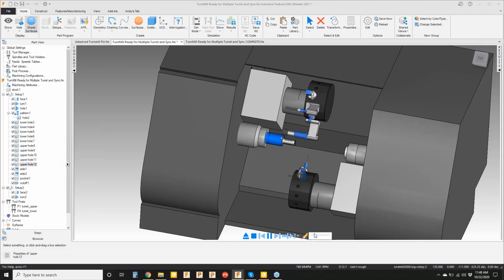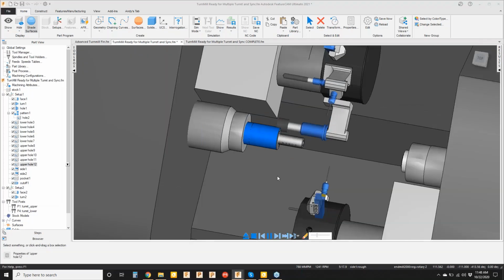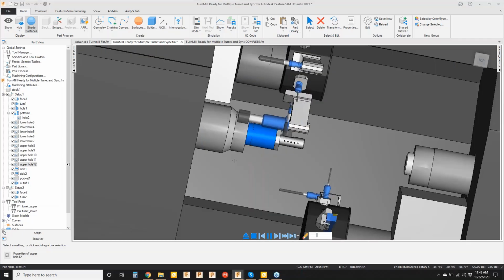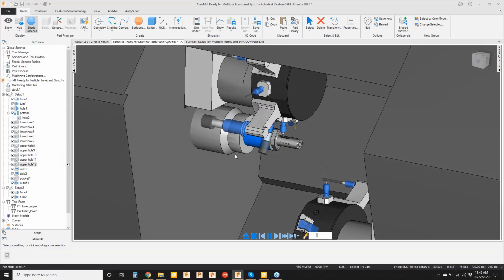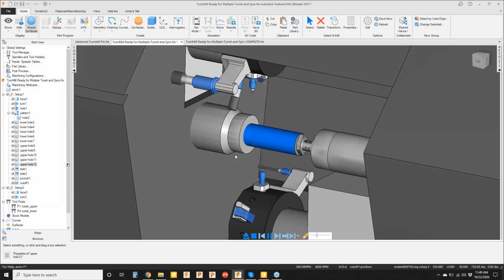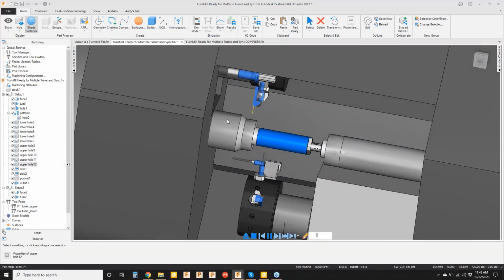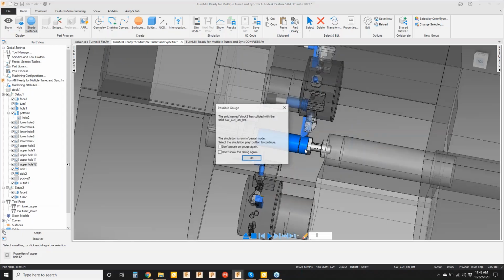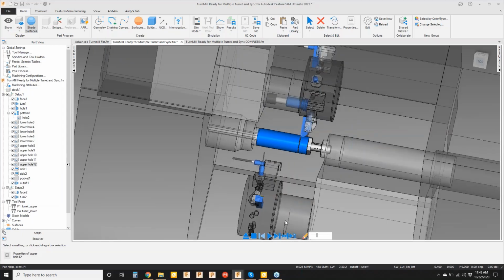So you can see C-axis motion. We could again lock that with that checkbox I talked about earlier. This is a feature we could lock if we wanted to for rigidity purposes or whatever your needs are. Simple checkbox. You can swap your tools out, whatever you need to do. So it's just like any other area of FeatureCAM in that regard, but we're doing something a lot more complex. So we got our cutoff, the transfer is going to happen, and you'll see that in this case we have a collision, so we would have to deal with that.